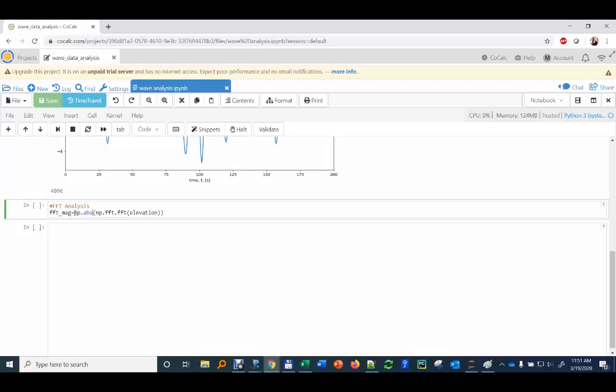And then to obtain, we don't want to have this spectral power, so then we have to multiply. This is also explained by this video if you need to know. Multiply by 2 divided by the number of points. Okay, so there we get the y-axis in my frequency diagram.